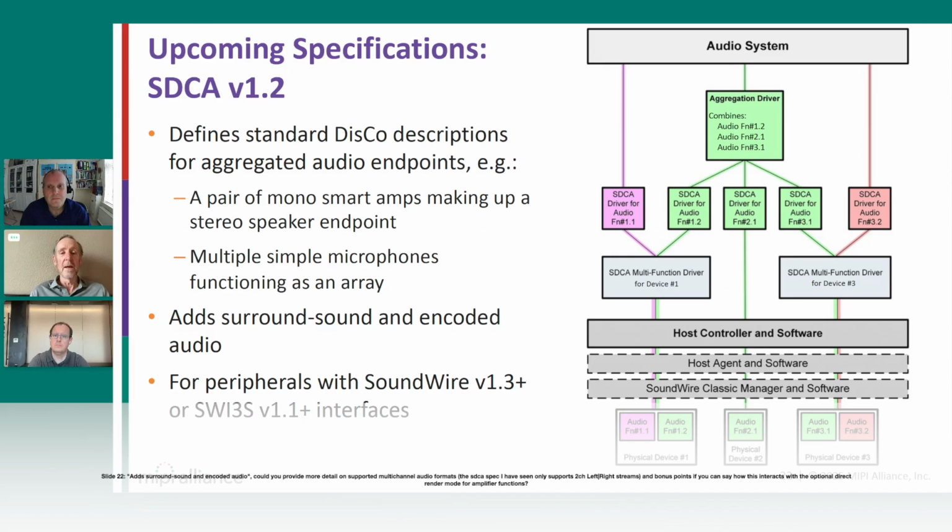additional reporting in 1.2, will allow the class software now to take, for example, AC3, which is a good one in that on SPDIF today, you really would expect to be able to take AC3 from a movie player and pass it straight out to the SPDIF interface.